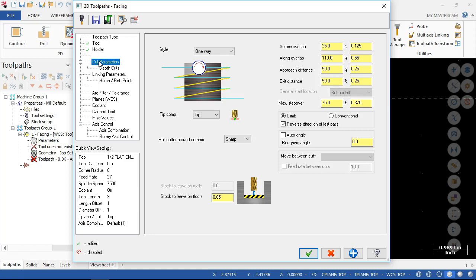All right, going into the cut parameters then, we're going to go one way, zigzag, or dynamic. So one way would be if we have an older machine, and as it reverses direction, the backlash compensation isn't quite there, and we get a swirl one way, and then we get a little bit of separation, and we get a swirl the other way.